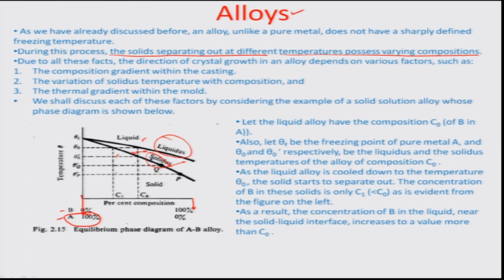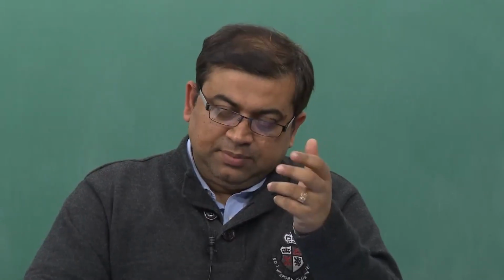Okay, one of the phases may not go into the solid crystal, and in the liquid form their solubility may be different. So, in that kind of situation, obviously the point where the solidification is taking place, which is also known as the liquid solid front, the composition would be a function of time, because obviously if the solid state is rejecting a part of the phase B, for example, because it cannot contain B beyond a certain percentage.